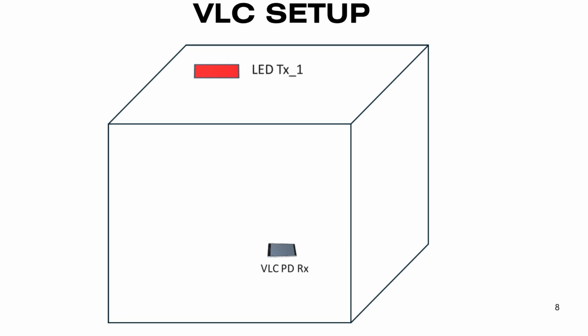One more important aspect is that the sensitivity of the photodiode greatly depends on the material it is made from. Like as we assumed a silicon-based photodiode, this type of material is easily adaptable and sensitive to both the LED-enabled visible light region as well as the upper frequency spectrum in the infrared region. It means higher frequency resources in the visible light wavelength region can be effectively exploited if there's no obstruction or interference in the light propagation channel between the transmitter and receiver.